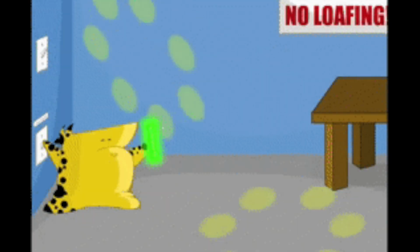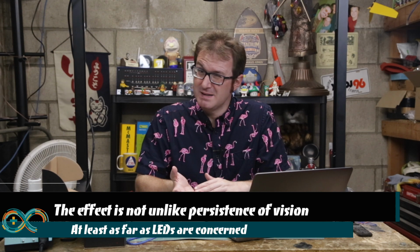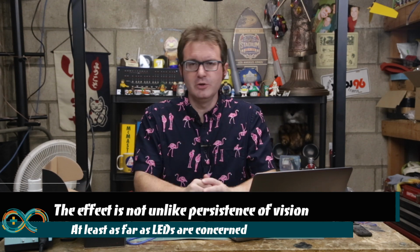If you repeat this on-off pattern fast enough with an LED, for example, what happens, practically speaking, is that the LED will shine at a particular brightness that's relative to that pulse width. Essentially, what we're doing is turning the LED on and off at such a specified rhythm that it simulates a level of brightness. Make sense? Clear as mud? Yeah, you'll see once we actually wire this thing up.